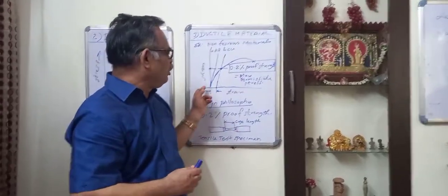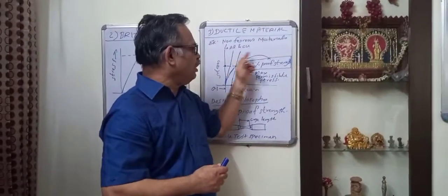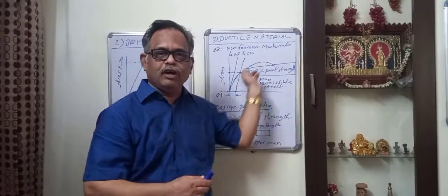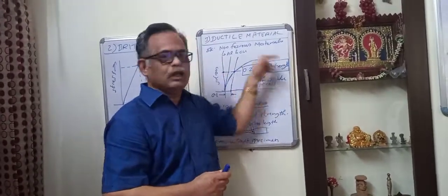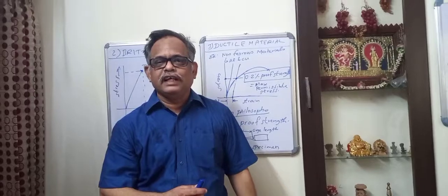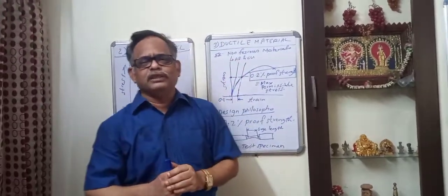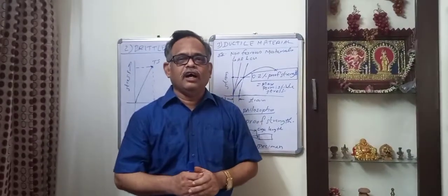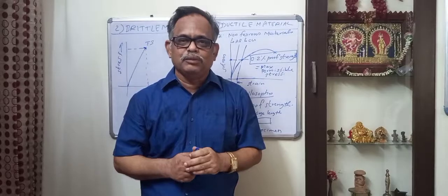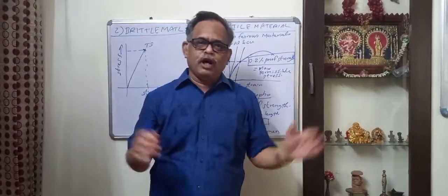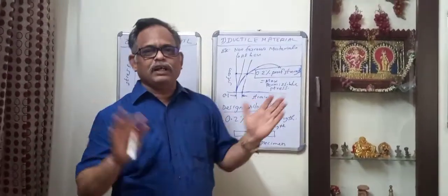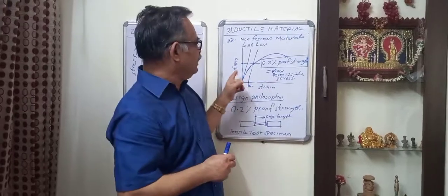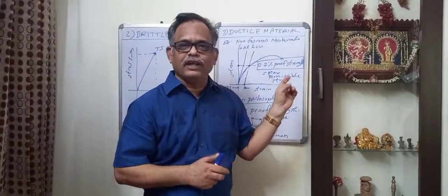It depicts a type of curve, something like this. So in such cases, for all boiler pressure part designs, the 0.2% proof strength is taken as the maximum permissible stress, wherever temperature is high and it is likely to show a characteristic curve like this.